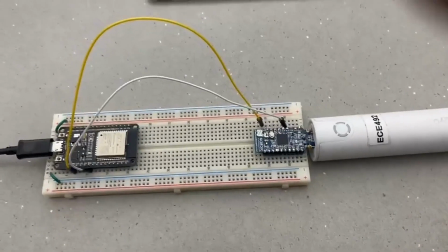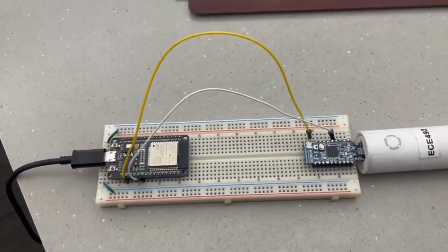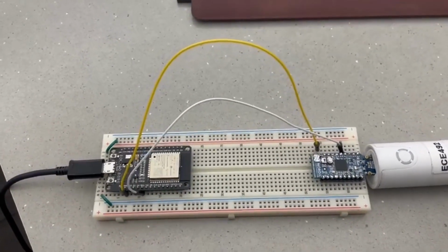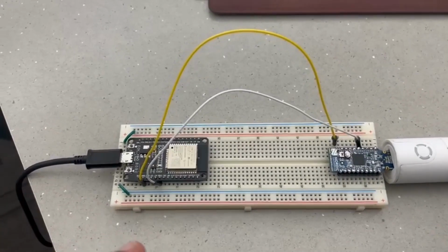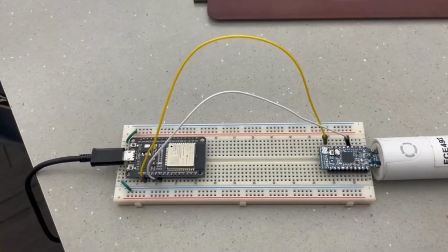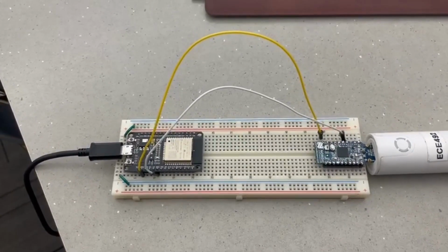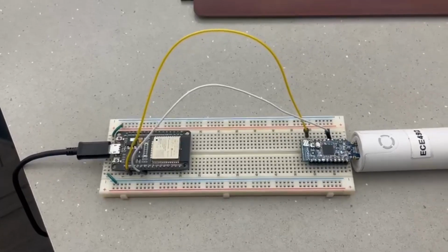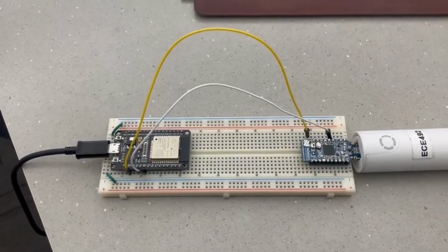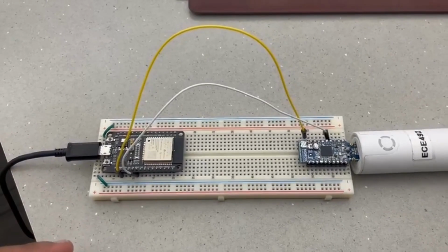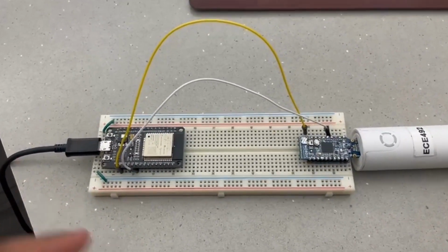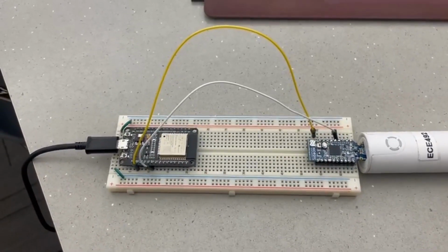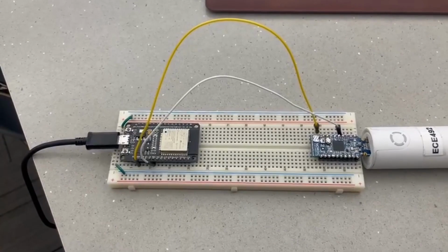And when it comes to the ESP32, as you can see, we're using a UART to communicate with the ESP32. And the ESP32, we went with it because it's readily available around the lab, and it comes with an amazing software development kit so that it allows us to rapidly develop. On top of that, for the firmware side, we are using FreeRTOS, and FreeRTOS allows us to run multiple tasks simultaneously.